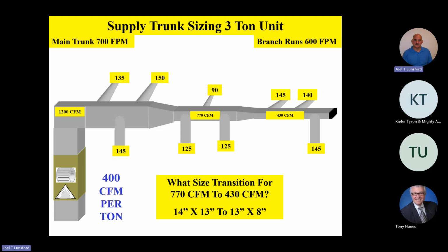And then right behind that is keeping your refrigeration system clean. You know, use nitrogen when you raise your lines up and all that stuff. Keep your refrigeration system really clean and dry. Get a good double evacuation. But if you'll do those two things, keep your refrigeration system clean and dry when you put your unit together, and give it the proper airflow at the proper velocity, those are the two top things that you can do to make a reliable, comfortable, quiet system.